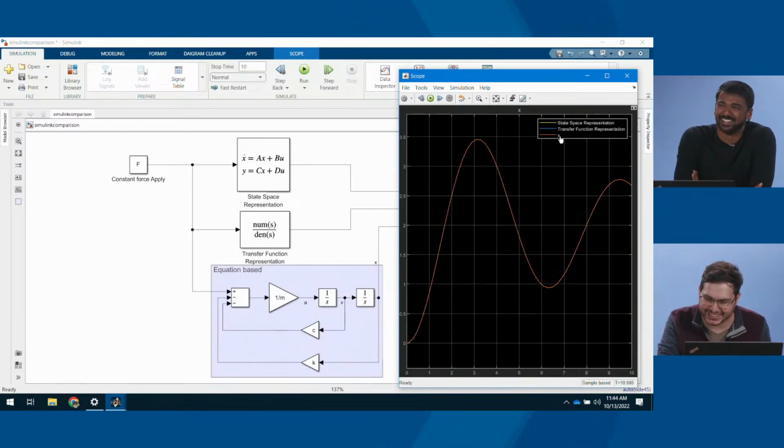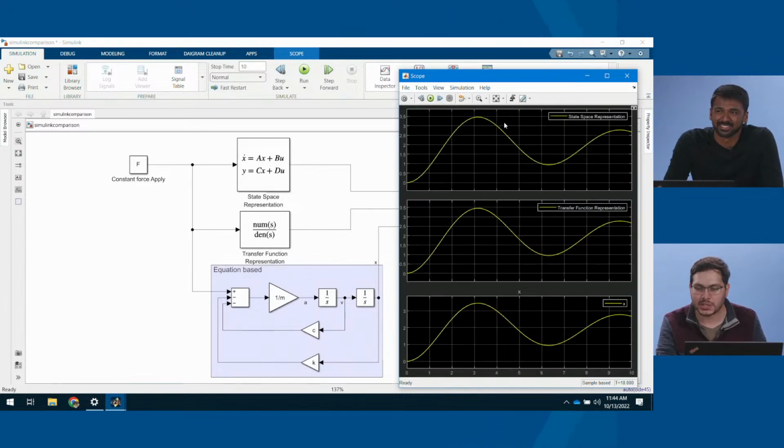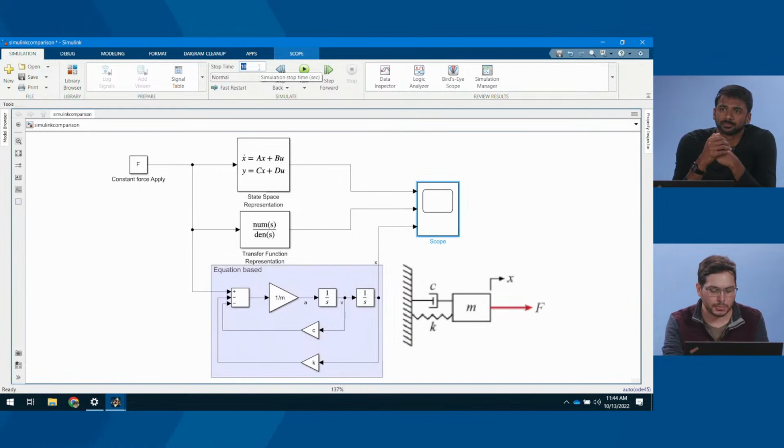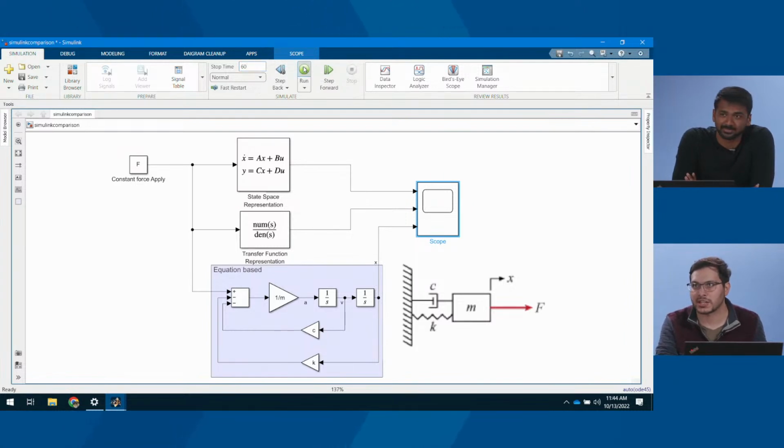They're all there. I just had it set out with the 3 so we could see all of them independently. But you can notice with the parameters I've got right now, I'm not really seeing the entirety of the behavior. So over here in the simulation tab, I've got my stop time, and I'm going to set that to 60 seconds. So I'm going to simulate 60 seconds of all 3 of these mass spring dampers. How long is that going to take, Sam? Oh, maybe a second. Okay, there it's done. Maybe even less.